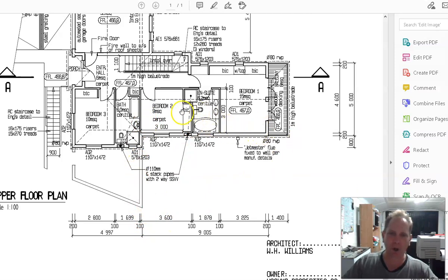The builder wants to know, windows are nearly always central, so don't dimension that piece of wall because it's to a window. Just leave it. The builder will know where to put the window. Okay. But your dimension text should be clearly visible. It should be off the line.